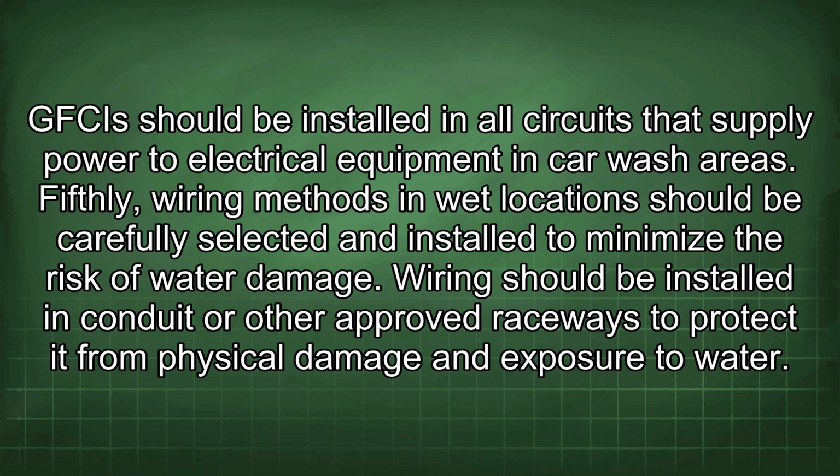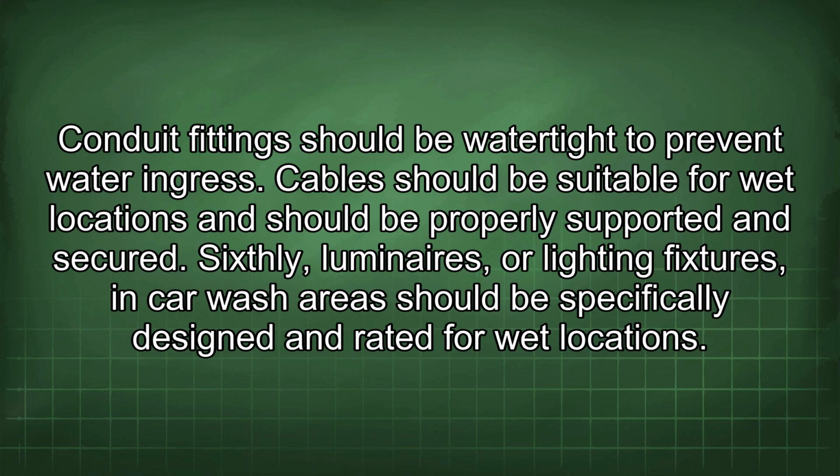Fifthly, wiring methods in wet locations should be carefully selected and installed to minimize the risk of water damage. Wiring should be installed in conduit or other approved raceways to protect it from physical damage and exposure to water. Conduit fittings should be watertight to prevent water ingress. Cables should be suitable for wet locations and should be properly supported and secured.